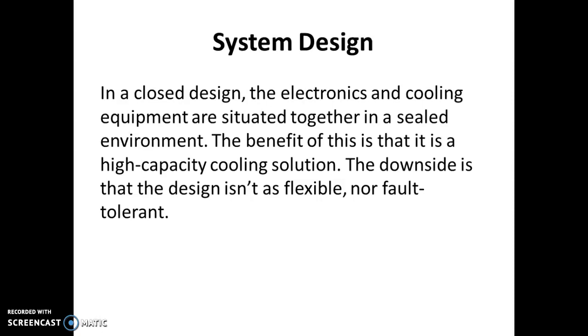The factors which we need to calculate the cooling requirements are, the first one, room size BTU. Room size BTU is based on the length and the width of that particular room. Then window BTU, equipment BTU, and lighting BTU. Lighting BTU is the total watts of energy being consumed by the various electrical equipments.